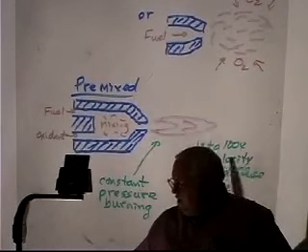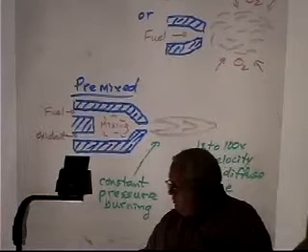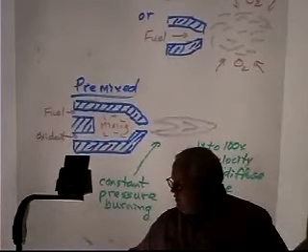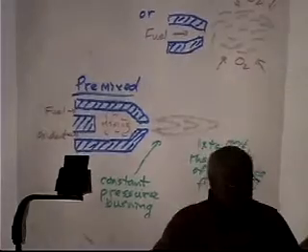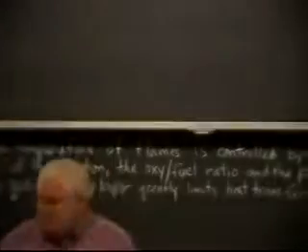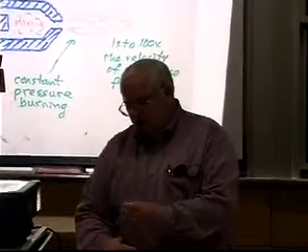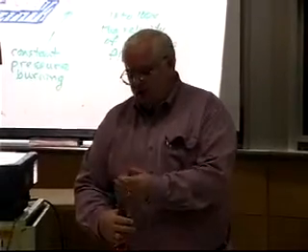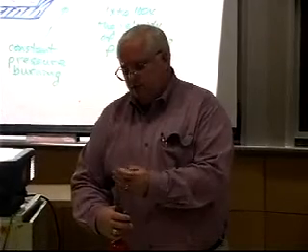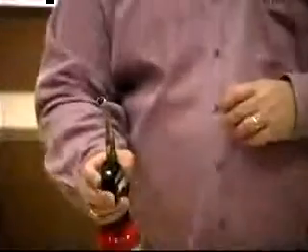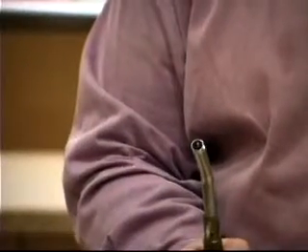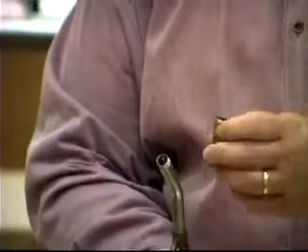That should be 10 to 100 times the velocity of a diffuse flame in a premixed flame. And I'll pass this around again in just a second. I do want to turn it on again. If you look inside this thing, you take this off, unscrew this, you can see some little turbulators in here. On the end, this is piezoelectric start. You'll notice that the nozzle is actually doing something. This thing doesn't want to keep burning when it's just coming out a great big hole here. It actually has a nozzle and it has some little fins in here.